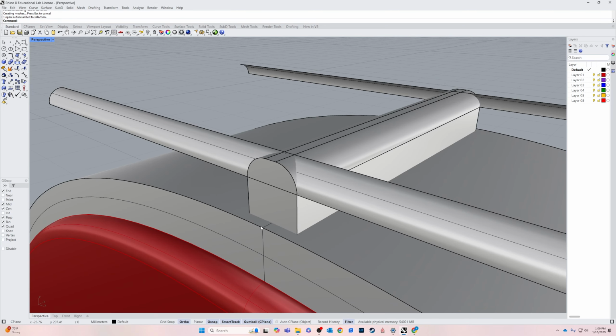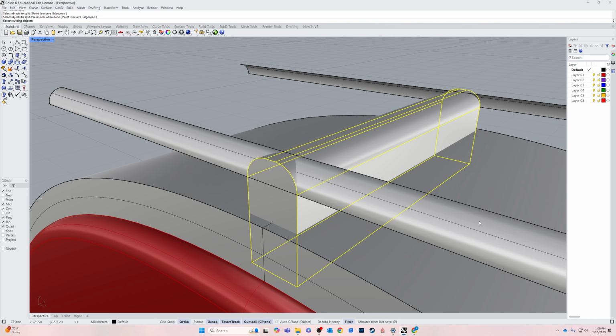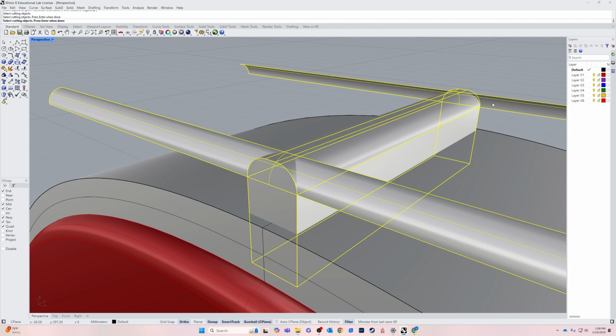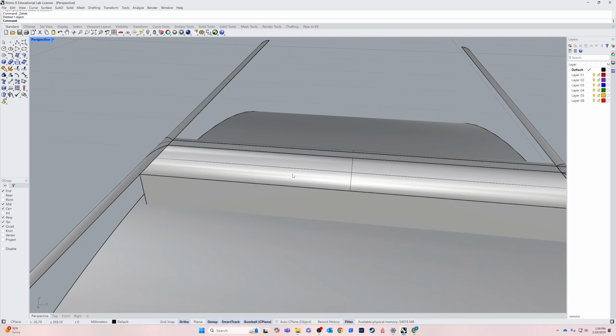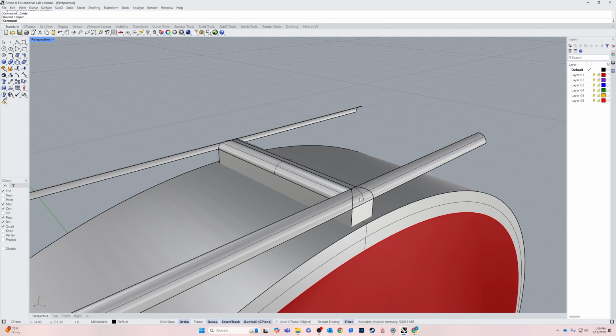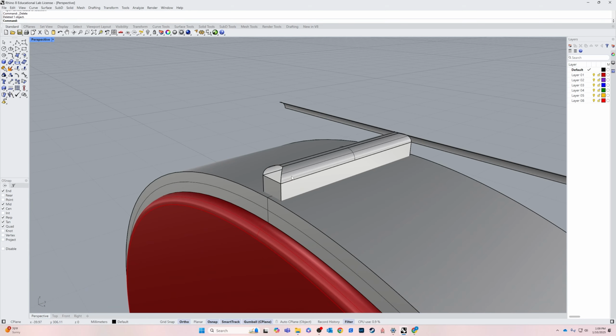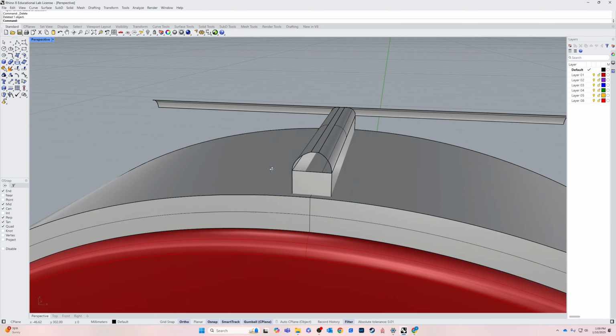But it gave me a cutting blade. So now I can split that section out. So split, enter. This object, enter. With this and this, enter. And what that has done is that it's cut off this section here. I can delete it and cut off this section here and delete it. But if I get rid of this, you'll see it's open. You can see through it.